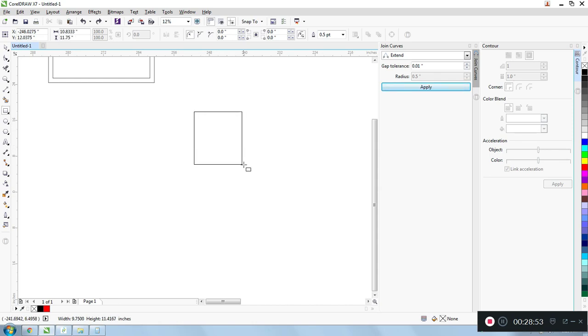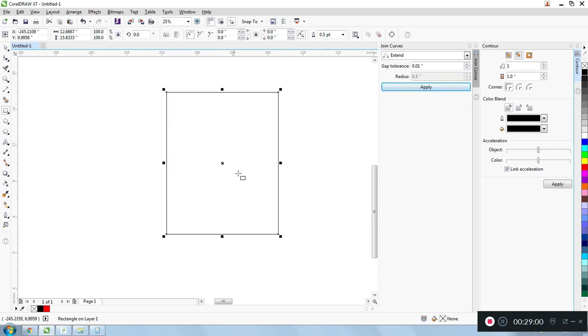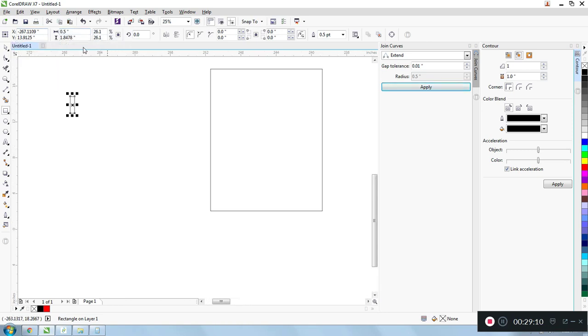and what I do and what many other people do is what's called dogbone. So I'll make kind of a mock part here. This is my base plate that I'm going to want to put a slot into. So we'll make the slot, and we're going to say we're using 1/2 inch material, 0.5 inch, and then we want our slot to be 5 inches long. Oops, I need to unclick the ratio. 5 inches long. So now we have a slot that's 5 inches by 1/2 inch.